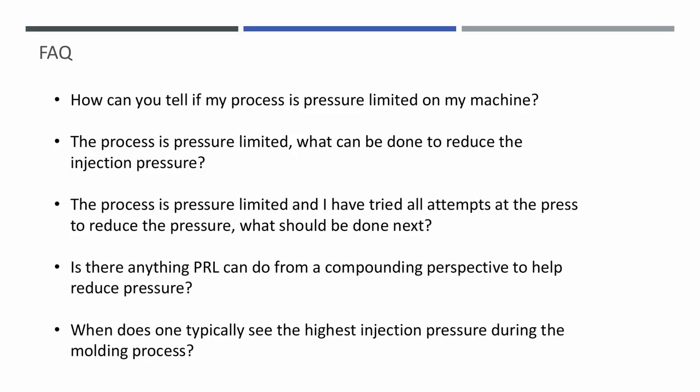Is there anything PRL can do from a compounding perspective to help reduce pressure? Yes, though they have limited impact, compounding in lubricant additives can offer some relief. Also, specific melt flow ranges can be targeted when compounding those end product lots and batches.